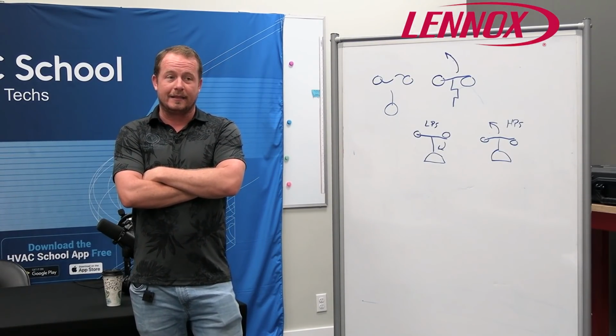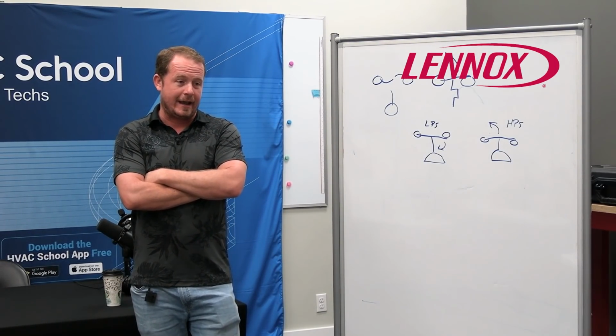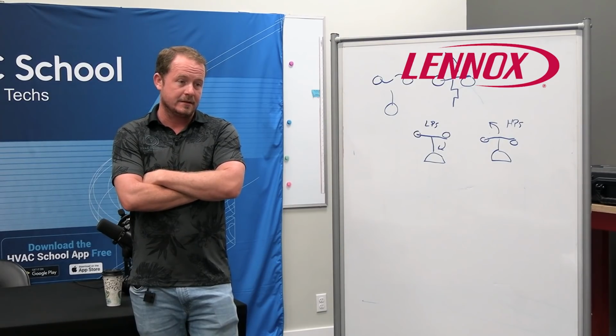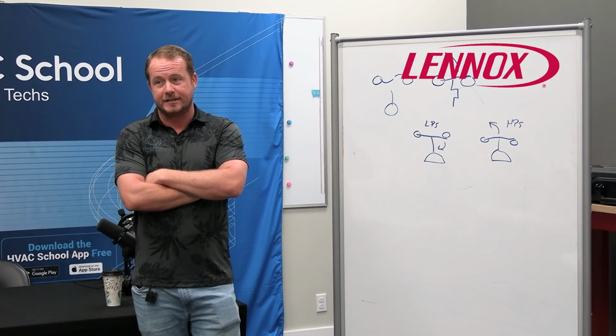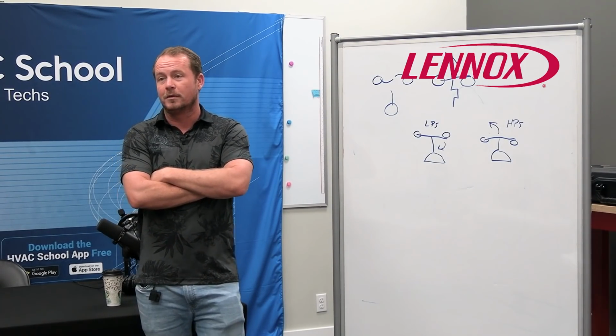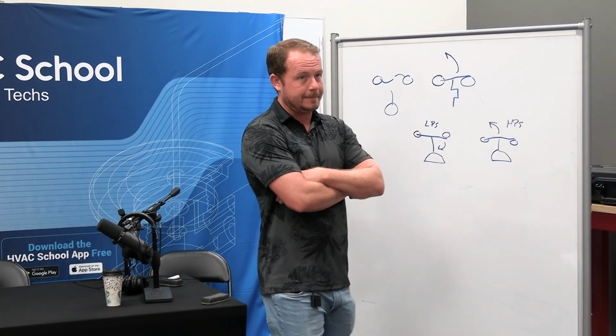And one unique thing about Lennox is that it has this lockout. If it goes out so many times, the switch may even close again, but it still stays locked out. And that's where you pay attention to the blinky board, right?